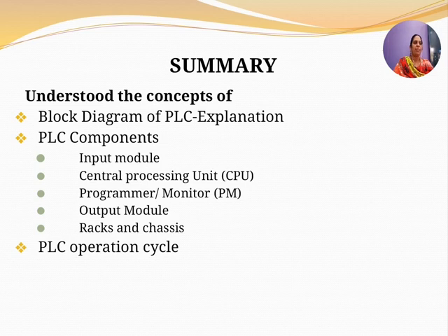The output module of the PLC works similar to the input module, but in the reverse process. Here it interfaces the output of the load and the microprocessor. So here the first section would be the logical section, and then your power section. When the logic high signal is generated from the processor, the LED will turn on and allow the light to fall on the phototransistor. When the transistor goes to conduction state, it generates a pulse to the gate of the triac. So the isolator block is used to isolate the logic section and the control section in the output module.